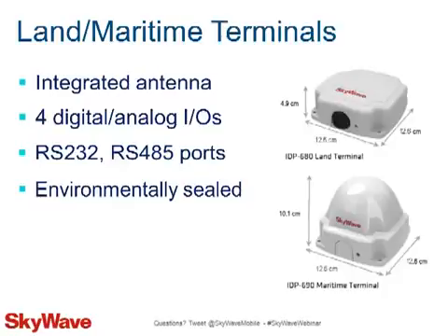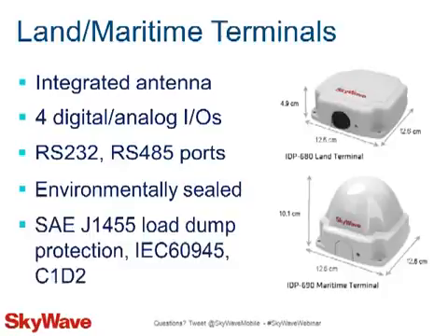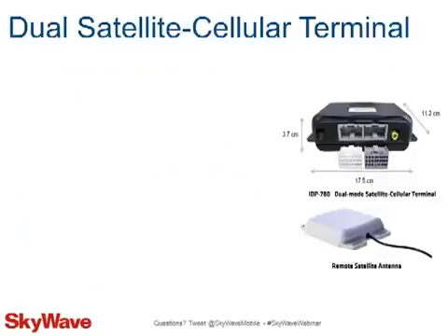And finally, it has already been certified by industry for a number of applications, like SAE J1455 for load dump protection for the transportation market, IEC 60945 to ensure that the terminal does not interfere with GPS navigation equipment on maritime vessels, and Class 1 Division 2 or C1D2 for use in hazardous locations for many oil and gas or SCADA applications.